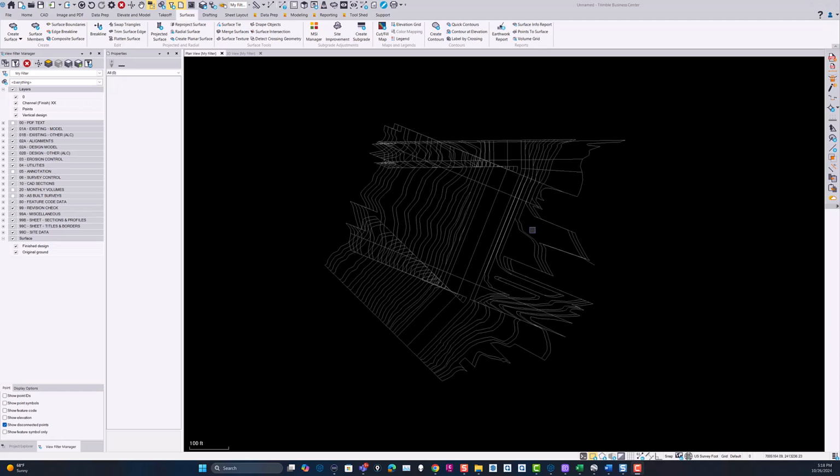This is an example of a project that I looked at a few months back, where the corridor model, basically this is an alignment going through here for a large trench, and the trench is quite wide, and then it has a series of benches that come out to existing, and the benches had to be wide enough to be able to get a wick drain machine onto the benches. And I was asked to help look at designing this and working through it.